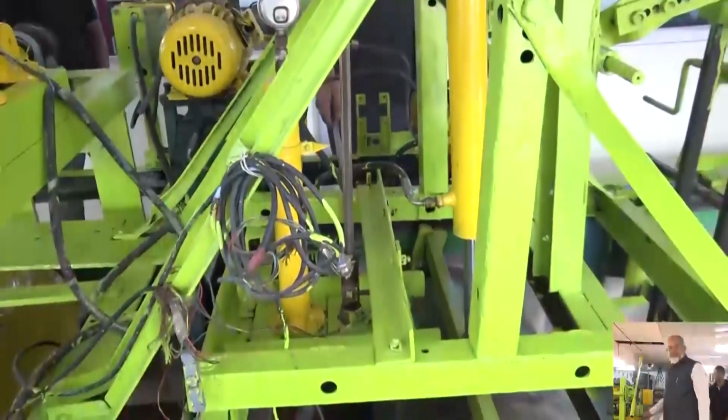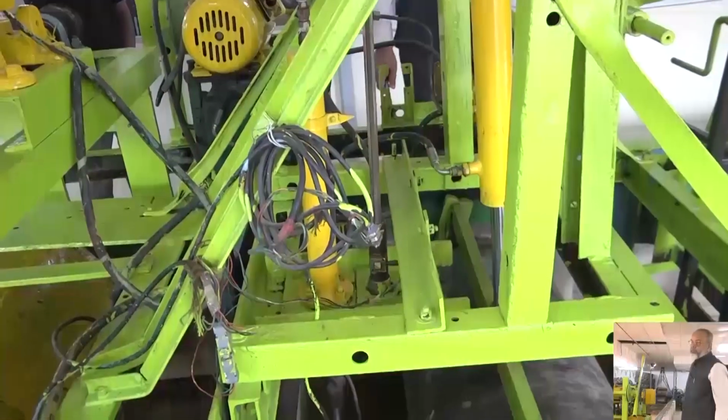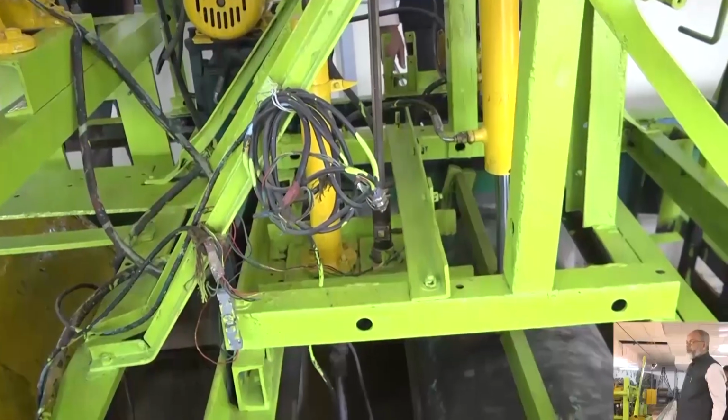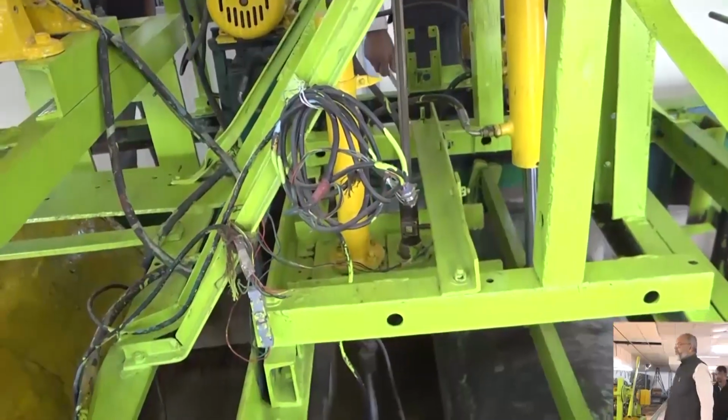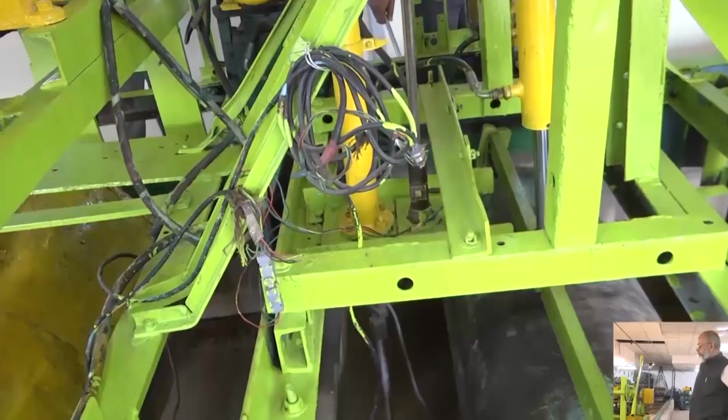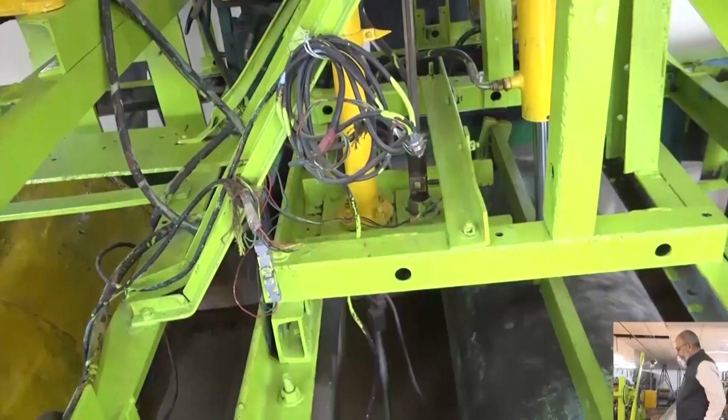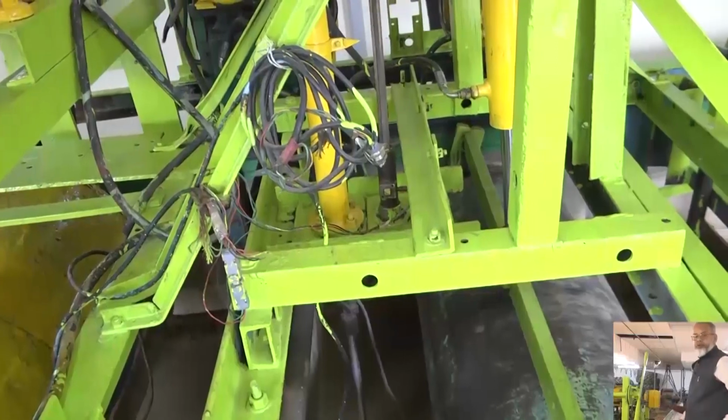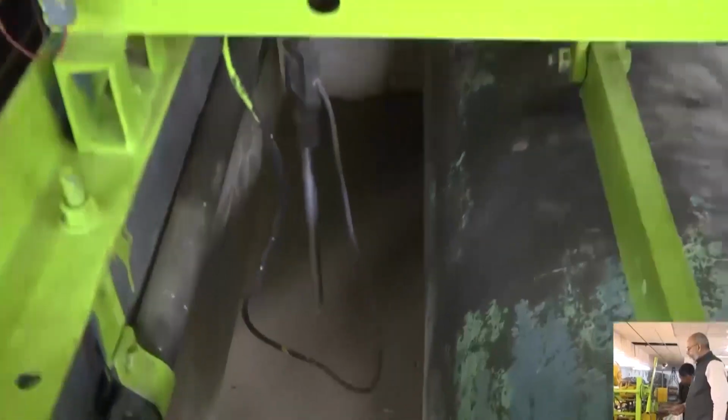Similarly, the load cell has also been calibrated. So the electrical output coming from it has to be expressed in terms of how much load or force you have applied. Now, I will show you how to measure the cone index. Initially the cone has to be pushed into the soil so that the base of the cone is just flush with the soil surface. Now, you can see the base is already flush with the soil. So, that is the zero line.